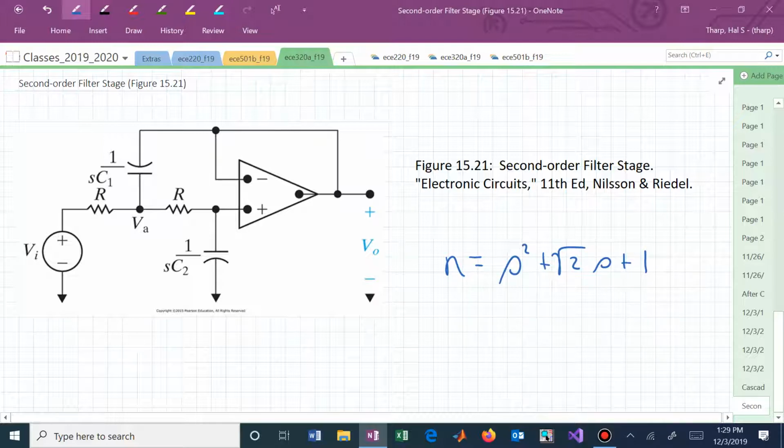And now you're going to have in these locations parameters containing R's and C's. Now you know what those R's and C's need to be in terms of their values. You find those, and those are now your original R and C values. You say, I don't want a bandwidth of 1 radian per second. I want something else. So you frequency scale. You can find new R's and C's based on our frequency scaling formulas.